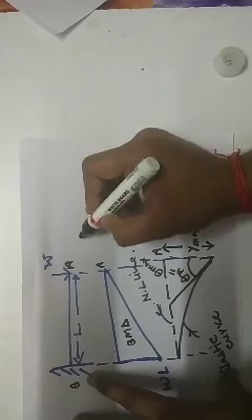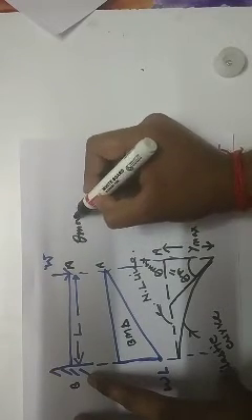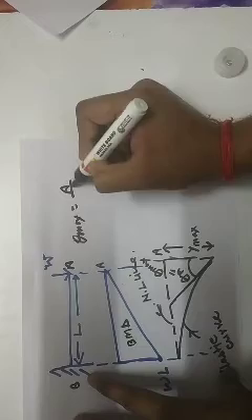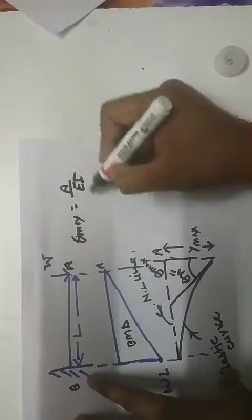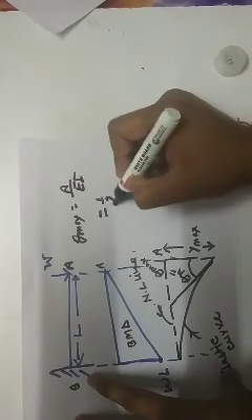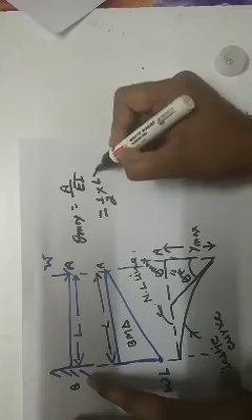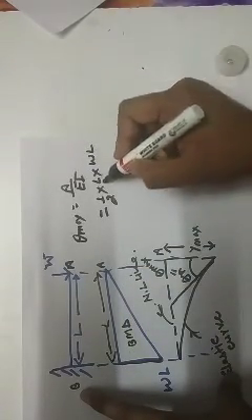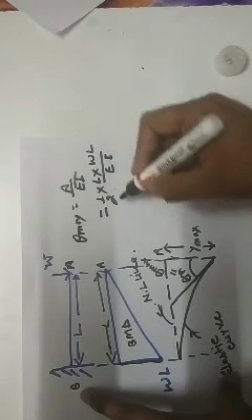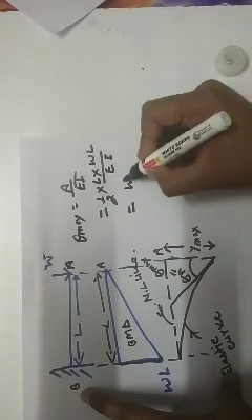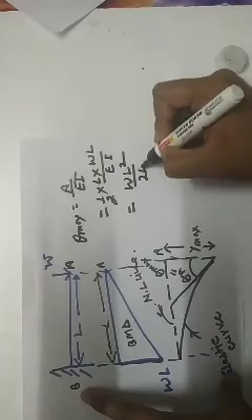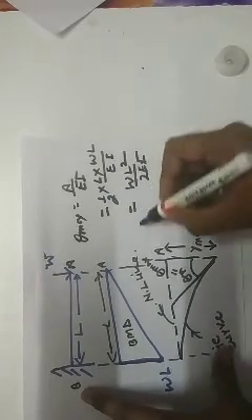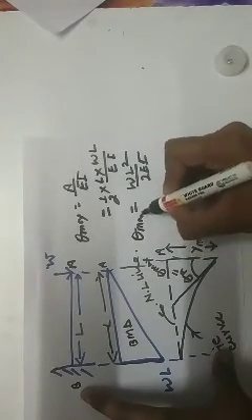With this bending moment diagram, this is point A. Then we know that theta max is equal to A upon EI. Then the area will be half, base is L, this length is L, and height is WL, right? WL upon EI. Then this will be equal to WL square upon 2EI. This is theta max.